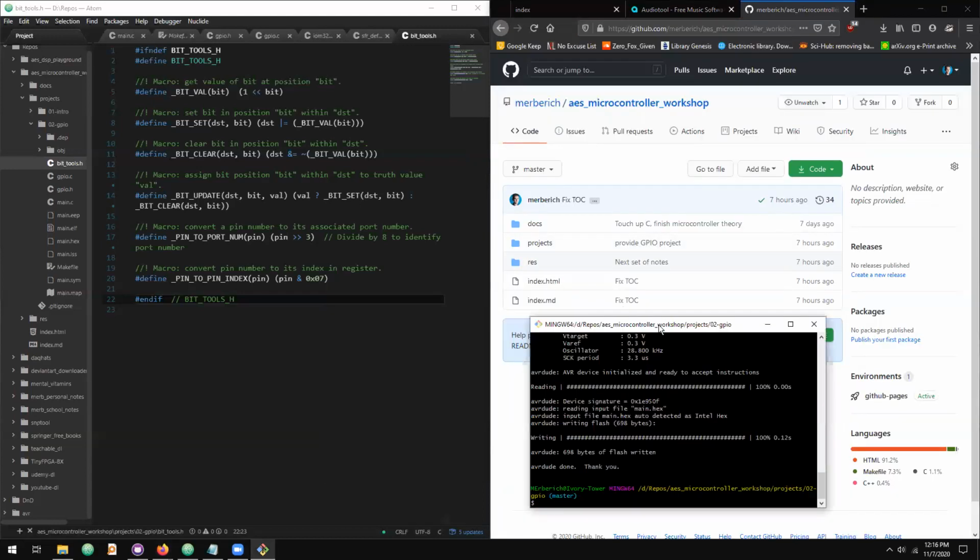That is strange. I guess the one that came with the kit is bad then, unfortunately. Sorry. Oh well. Also, you could try swapping out the cable next. Sometimes it's the really silly things. And if there are any pin headers on there, make sure that those are connected the way that they should be. I don't think the Arduino header has any default jumpers either, especially from the kit.